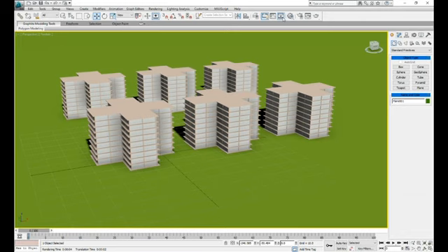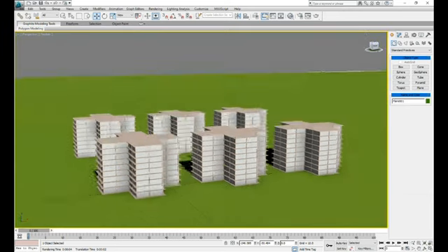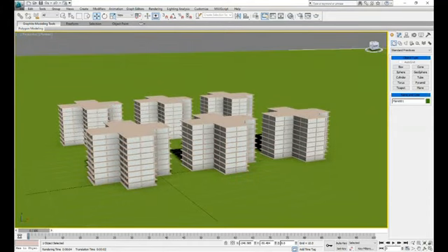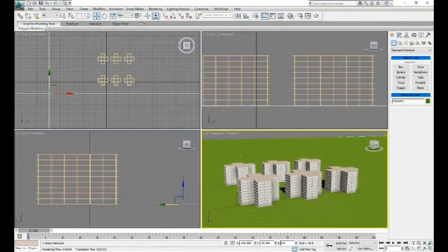And again, based on architectural standard of shade and shadow, we have 2 types of shadow. That is 45-degree in the morning, that is 9 o'clock. And we have 45-degree also in the afternoon, that is 3 o'clock. So if we say 9 or 3, we can create shadow for this one. So imagine this is your building now. You want to render this one in perspective. So how will you put lights for this one?